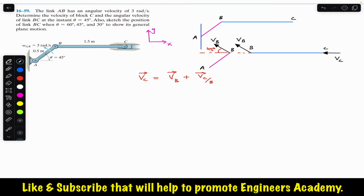So let's say this is omega BC. If you are not sure about the direction of omega BC, our answer will tell us whether this omega BC is right or not. The signs will tell us. But from now we can think that if this point B moves in this direction, this end B of BC will go up. So from our point of reference, it will appear that C has moved in the downward direction and point B has moved in the upward direction.